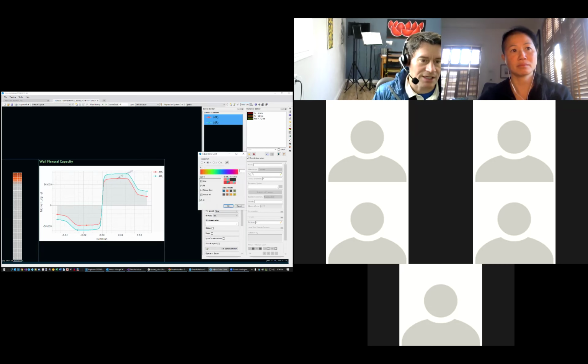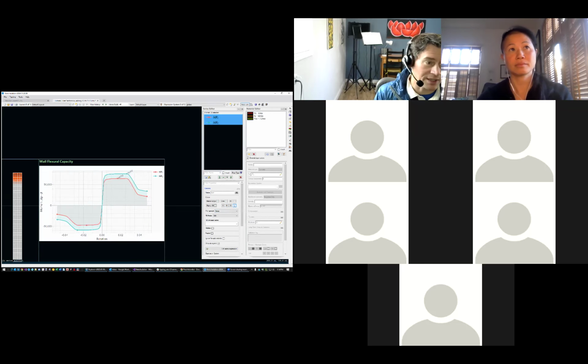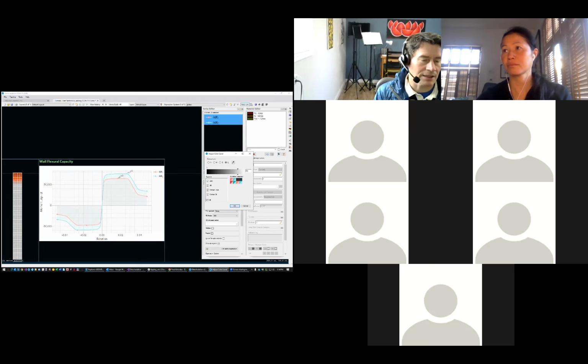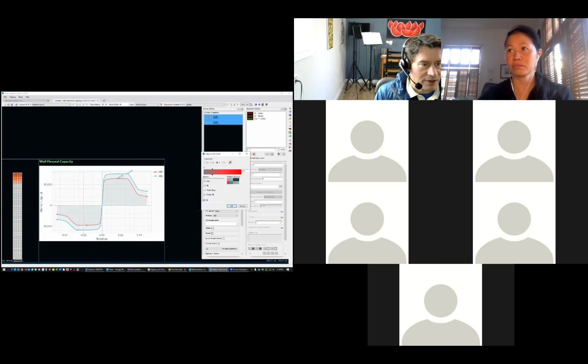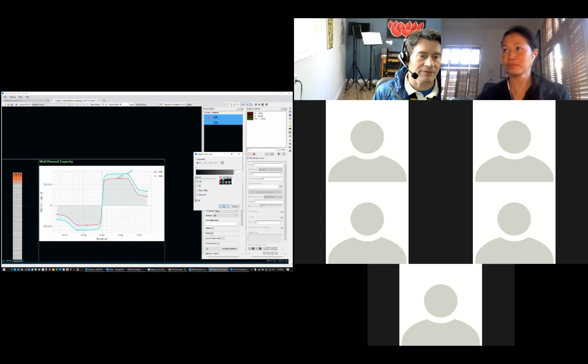And I showed in here that you can control all kinds of attributes of the series. You can change the hue if you wanted to, and they'll stick with the same hue. Or let's say you didn't want to change the hue, but you just wanted to lighten them both up, but keep the hues the way they are. You can just click the L and slide the L along. And saturation is going to give you either all the way to gray or all the way to fully saturated, or transparency, A for alpha. I don't know why it's called alpha, but that's the way it's called in programming world. And you can shift the transparency along that way.